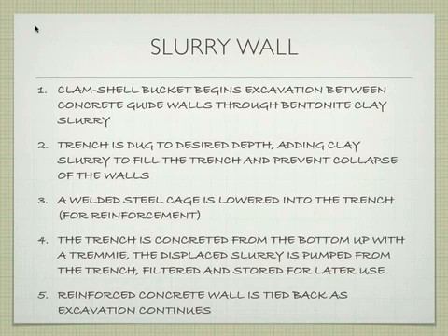Was there a question? No? I'm sorry. Okay, so you're going to start with this clamshell bucket. Sometimes it's between two beams that you've cast on the ground in concrete just to keep it straight. You can imagine working with a clamshell bucket would be difficult to keep straight if you didn't have some guide to work with. Then you're going to add this bentonite clay slurry, which, like I said, is just like a really thick mud kind of thing, but it's slurry enough so that you can dig through it and pull up your earth. Does that make sense to everybody? Okay, I'll show you some pictures in a second.